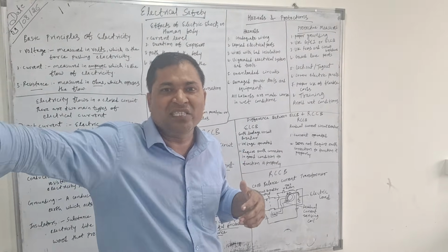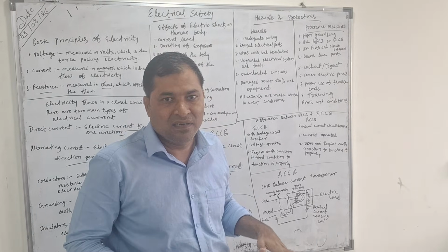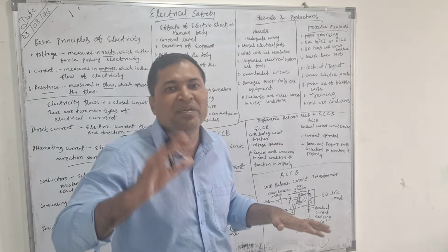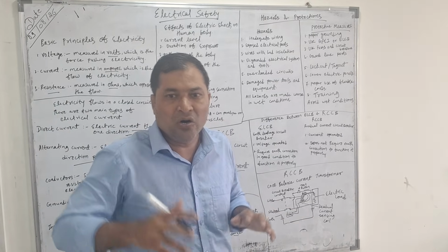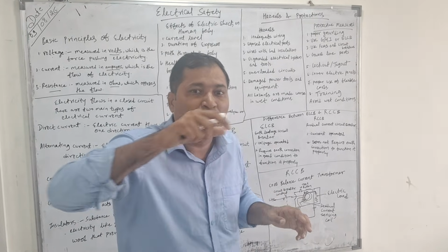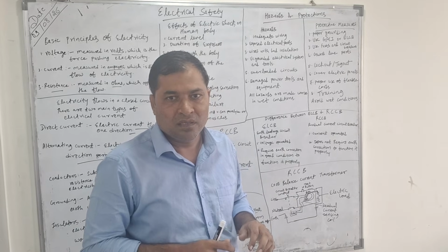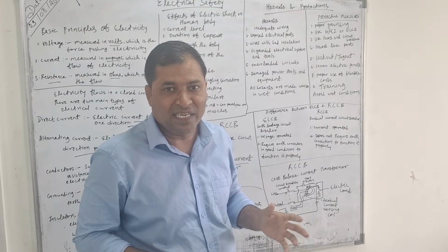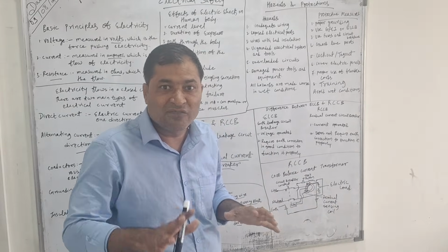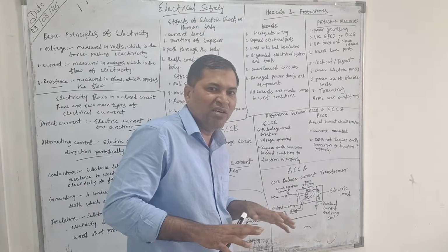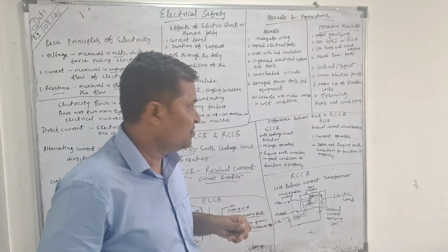Do not try to touch any electrical parts because the condition is already wet and you are working over there. You may be in a dangerous condition if you touch any live electrical equipment, or if you try to put plugs into sockets, because of the rain or the water collected in your work area. That is very important. Never touch any electrical parts in wet conditions.